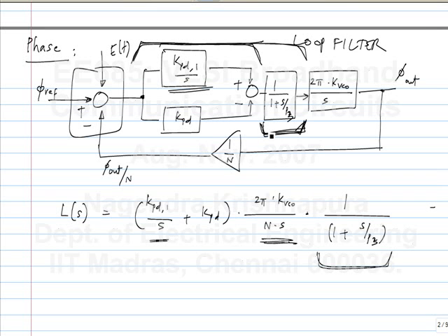The phase difference between this and this should be 0. So if the inputs to the 3-state phase detector are coincident, the output will be what? 0. When I say output, I mean up minus down output. That will be 0, right? Is that so or no? If the input to that is 0, why will the voltage keep varying?